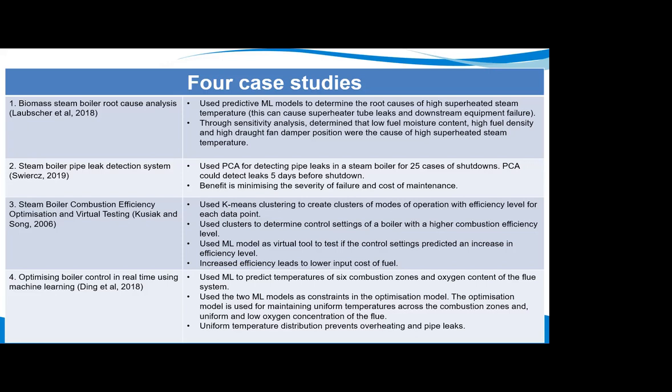And the uniform and low oxygen concentration of the fluid is an indirect measure of your combustion efficiency. So the lower the oxygen concentration of your fluid system, the better your combustion efficiency.